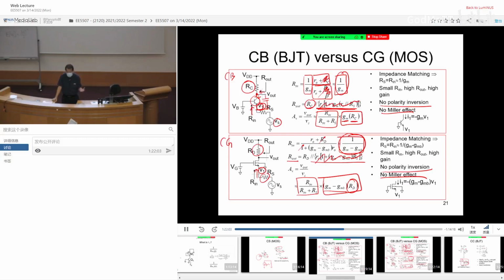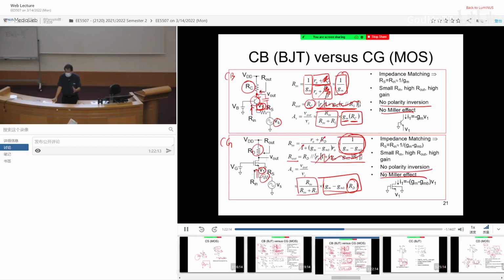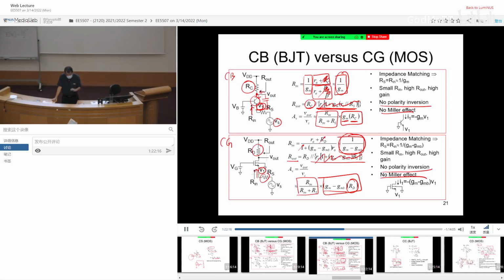Antenna is 50 ohm, TV antenna 75 ohm. Some people design a matching network, so that 50 ohm, after going through the matching network, gives you a resistance of 200 ohm, 1 to 4. All this tells you that in RF, input resistance is never big, and this gives you a way to exactly match this impedance.